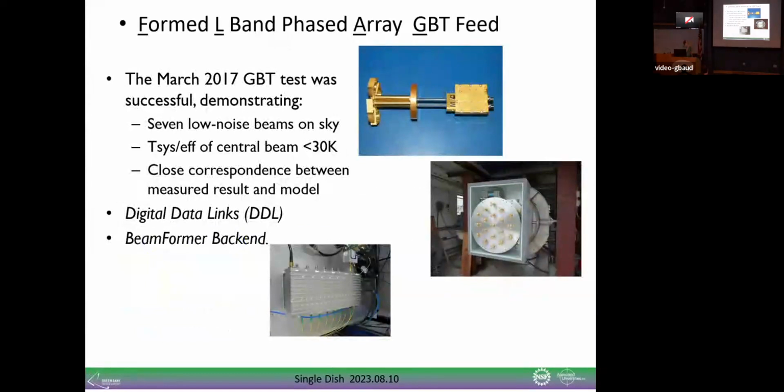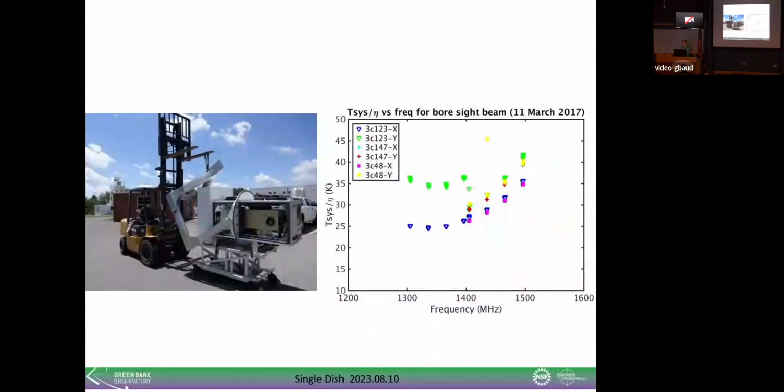We had a demonstrator; we built one here at L-band. It requires a lot of digital signal processing and understanding of the baseline and calibration. That's one of the drawbacks right now: it's difficult to use and difficult to calibrate. It was about a factor of 7 better than the L-band feed for mapping speed, but it's so complicated to use that we need more beams than the 7 to make it a viable instrument.